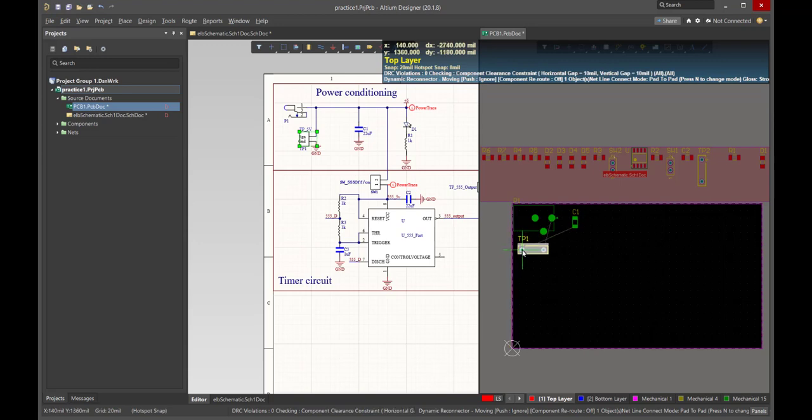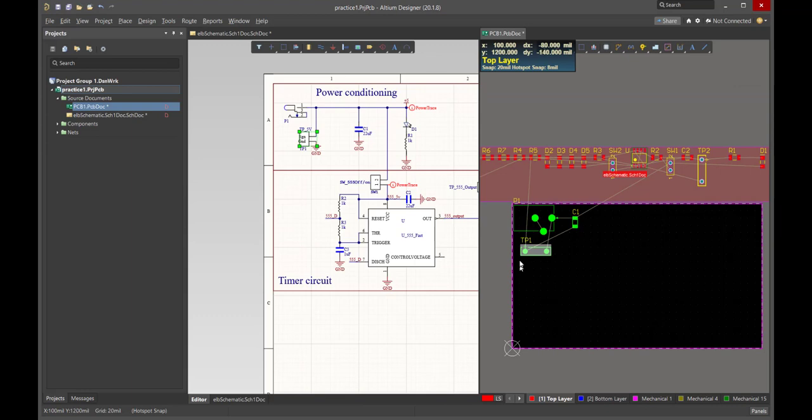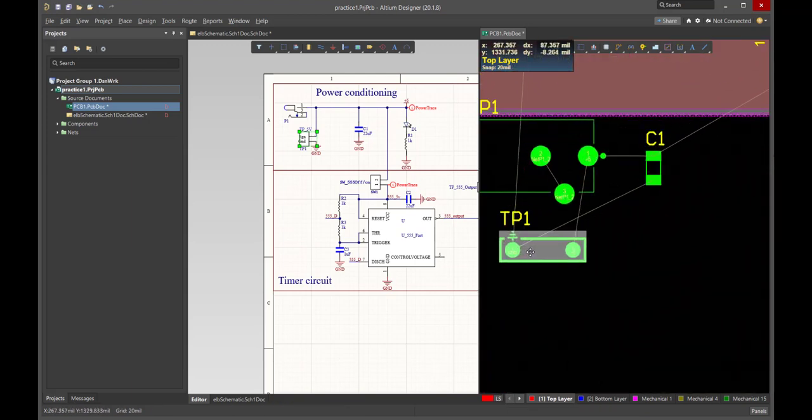And personal preference doesn't really matter, but I like having the ground of the 10x probe toward the outside of the board. It just makes it easier to remember. You'll notice on the 10x probe, in the footprint, we have a little ground symbol, which is great. That's going to remind me, oh yeah, the 10x probe has the signal on this side, the ground is going to be on the outside direction. And that way, when I'm probing the board, I don't have to think too hard. It's one less risk site to worry about. I always know, ground is to the outside, signal's on the inside.